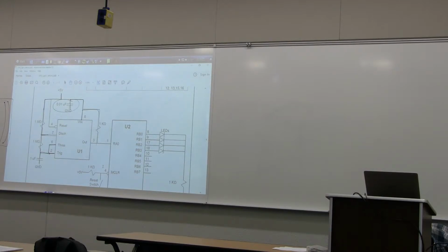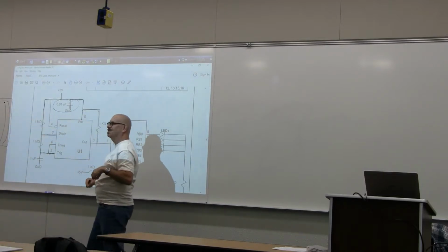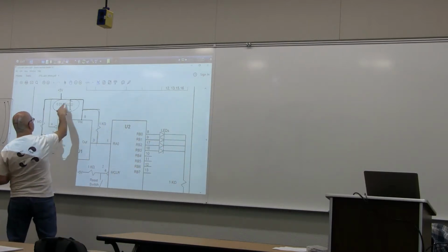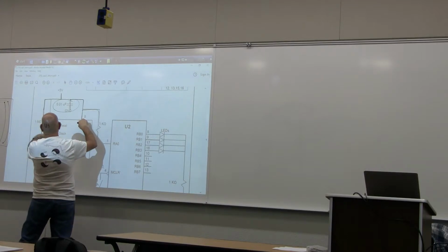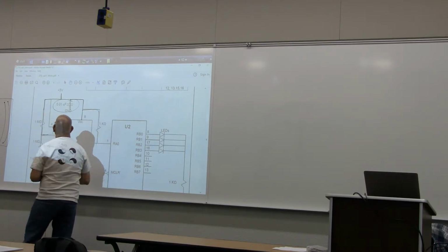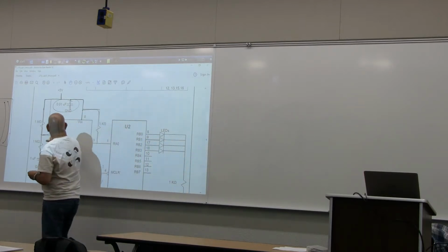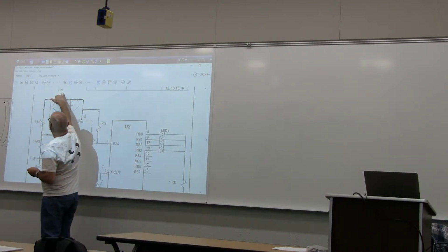So I'm laying it out kind of the way the picture is laid out, but I'm keeping my wires as minimal as possible. There are a lot of other ways you can do this, but if you take a wire from pin 2 and bring it over here, and take a wire from pin 7 and bring it over here, and then run a pair of wires from there up to here and put a resistor up here, it's just more wires to get in the way, more things that can get pulled out. And if you start trying to get fancy and say, well, this is actually going to connect to pin 8, and so you just put a resistor between here and pin 8, when you're trying to debug, that's not really what this circuit is saying. The first thing it's saying is that pin 7, 1 mega ohm resistor, 5 volts, right?